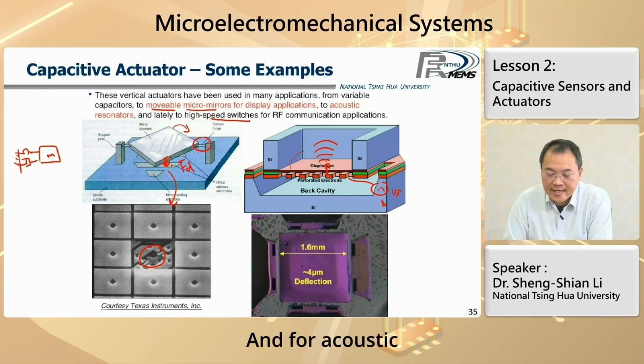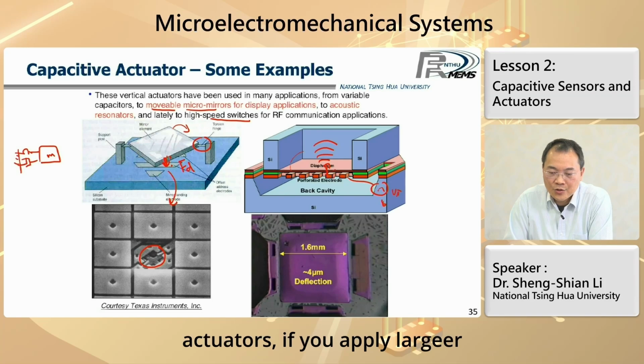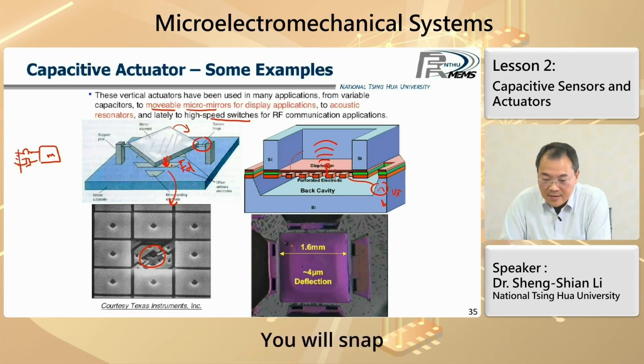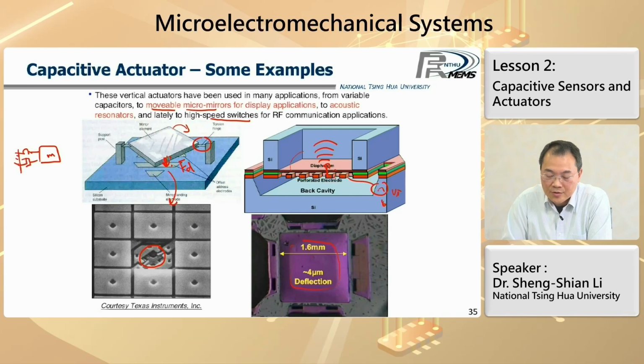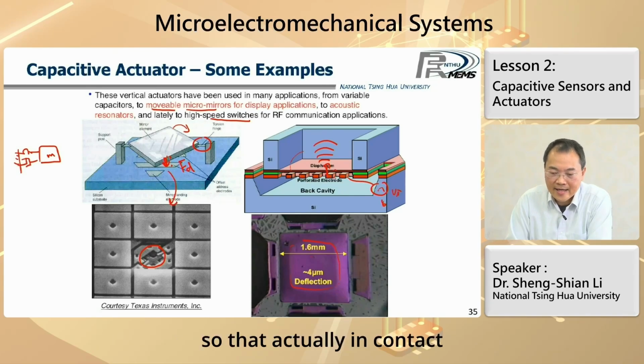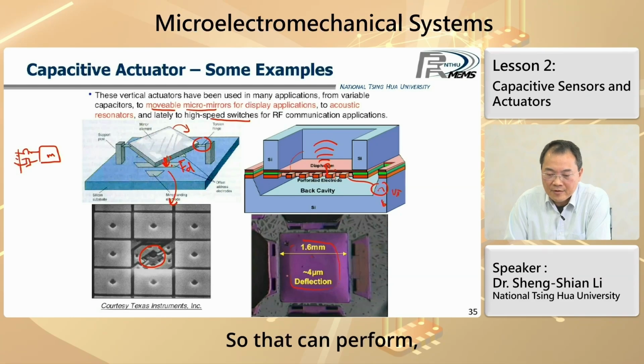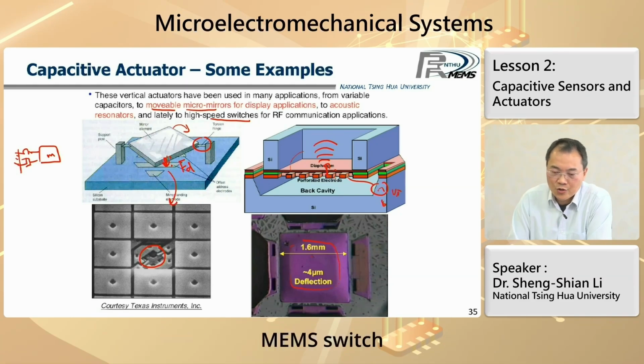And for acoustic actuators, if you apply a large voltage, you will snap the whole membrane down to the bottom electrode. So they are actually in contact. So that can perform not only as an acoustic speaker, but also as a MEMS switch.